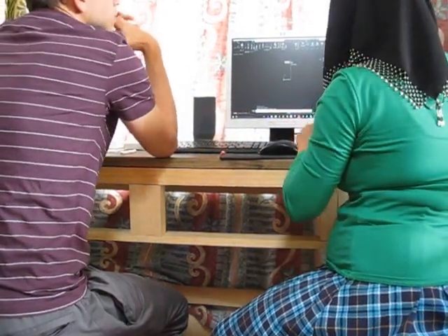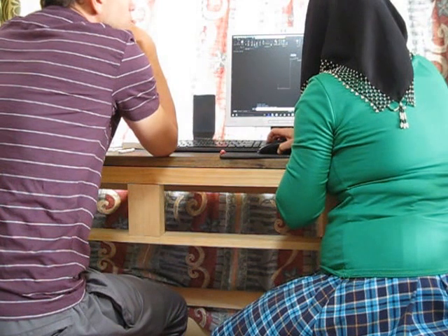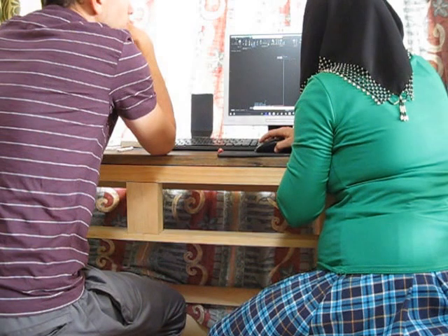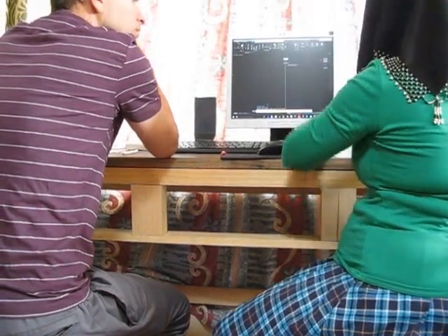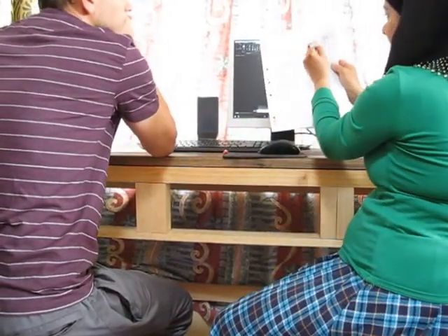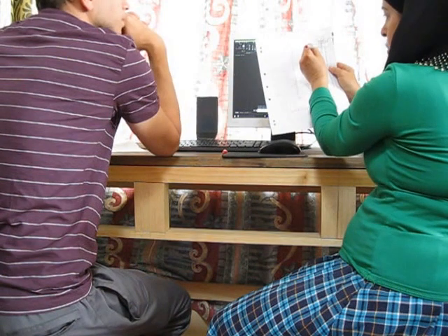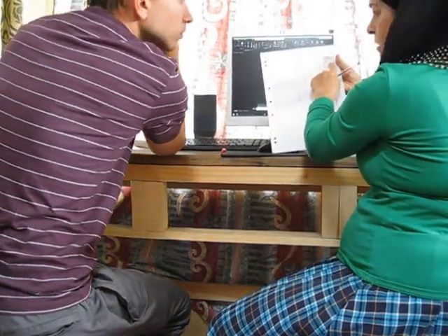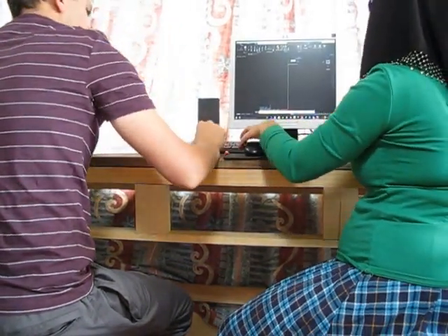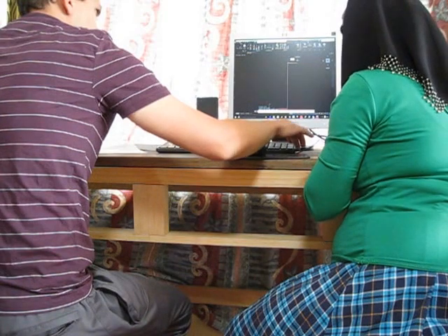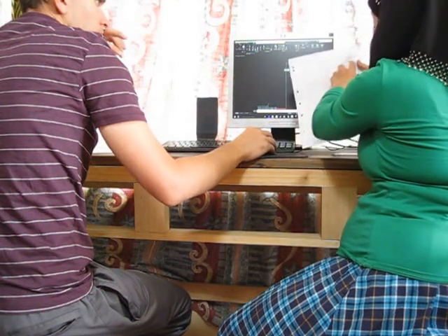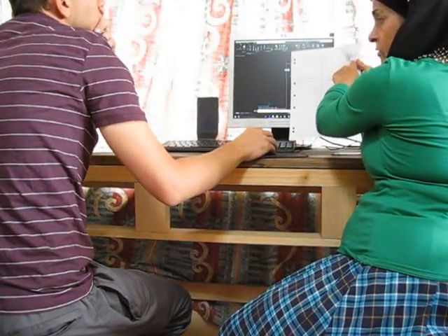Okay, so where are you now? I scroll the mouse to make it a little bit bigger. So I am right now in this corner, the left corner of the brick pier. So what is the best place to go now? Go to the right. How much do you want to go to the right? 230. Can you please go to the right side? You type 230, and it draws the second part of the top of this pier.